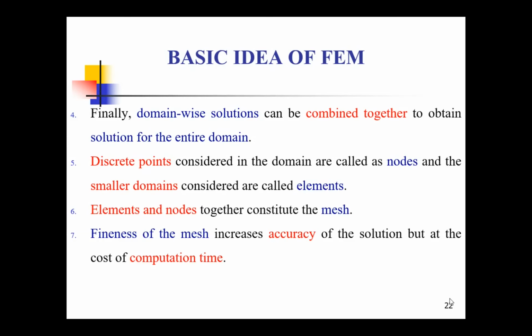If I am going to consider a finer mesh size, for example, 1000 mesh size for a small component, consider this as a finer mesh. If I consider a finer mesh, then obviously the accuracy of my output will be higher, but at the same time the computational time will be higher.